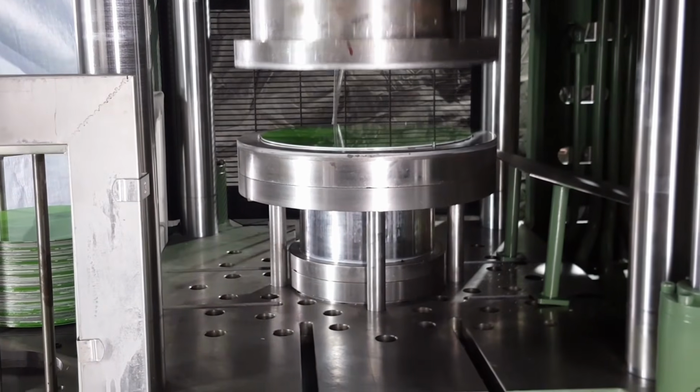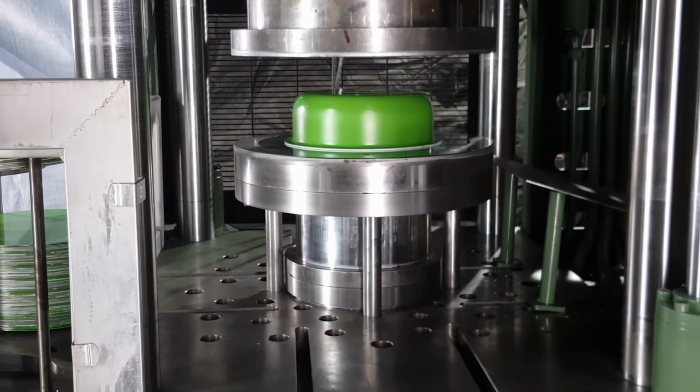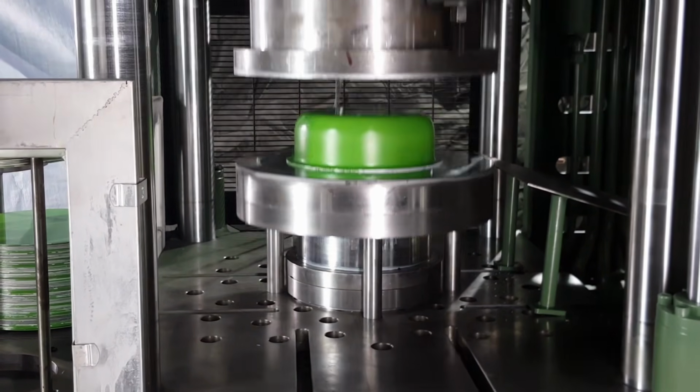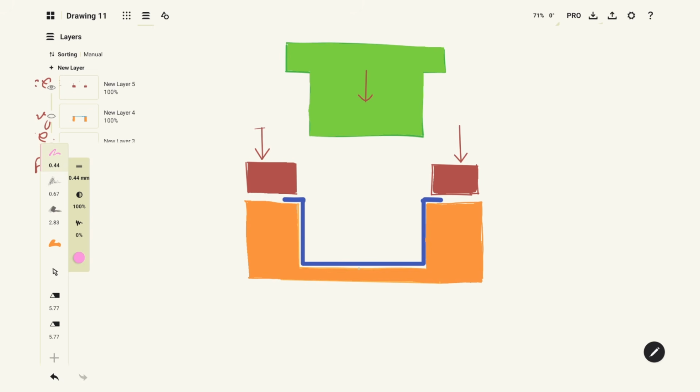But before that, let's think ahead. What if in future we want to automate this process completely? Imagine using an automatic loader to place the blank sheet and keep sliding out the final product after the drawing. So with this current tool design, this won't be easy. Why? Because the final product sits inside the die after the forming. So we cannot simply slide it out.